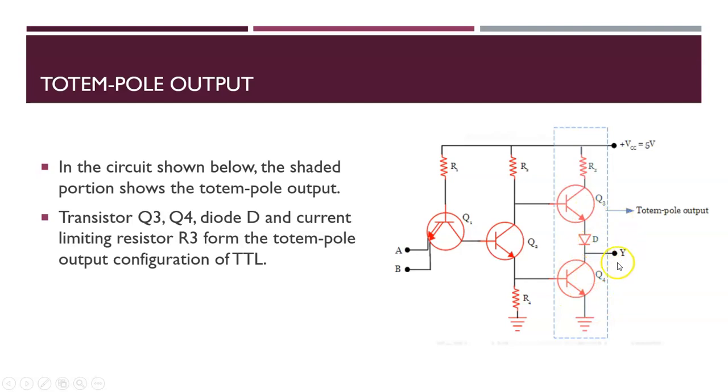If there won't be any current flowing through this circuit, it will be zero current by this transistor being off. When this is off, there is an open switch, and negligible current will flow into the base of this or to the collector of this transistor Q4 and the circuit, even to the load.